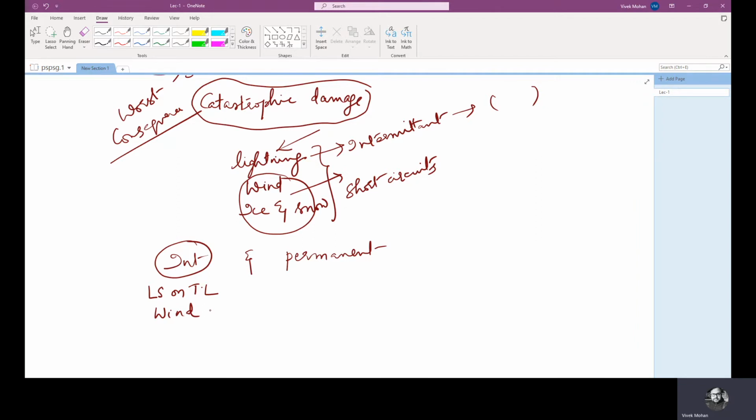If the arcing happens for a prolonged period, then the surrounding air is already ionized. That is why there is arcing. But the air itself acts as a conductor. Then what happens? The arc is maintained by the power in the line. If there is high power carried by the line, then the arc is maintained. Then the protection system responds by removing this power from the line for a period of time.